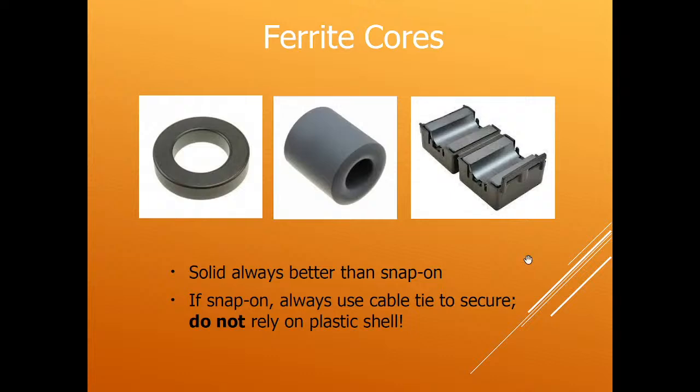And if you do use a snap-on core, do not rely on the plastic shell to hold it together. I mean, it might hold it together for 5 minutes while you test it, but if you decide that it's doing the job that you want, always put a cable tie around it so that it holds it together, because over time, that plastic shell will creep and the halves of the core will come apart, and then there'll be an even bigger air gap in it, and it'll completely lose all of its efficiency.